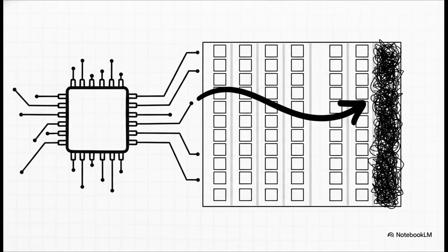Now, here is a fantastic pro tip for finding exactly which IC is broken among the dozens scattered across a board. Driver ICs usually have 24 pins, with 16 output pins sending signals directly to the LEDs. This means one IC controls exactly 16 columns of LEDs. You can literally just count the pixels across the board. If a color block appears right around the 15th column, boom, you know it's the very first IC in that group. It is a beautifully simple mathematical map straight to the faulty chip.